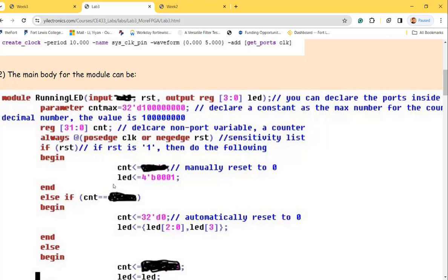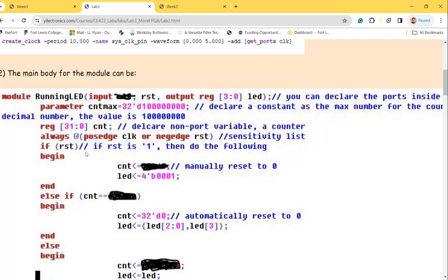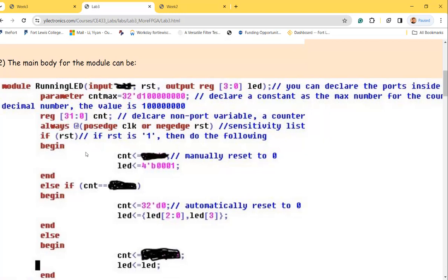So you can see whenever reset is 1, I think there's a bug here. It doesn't really matter, I think it's because of the bouncing back and forth. I'll let you guys try posedge as well, because I'm using if (reset), which means if RST is true, with 1, it's doing these things. It's actually a rising edge, but it worked.